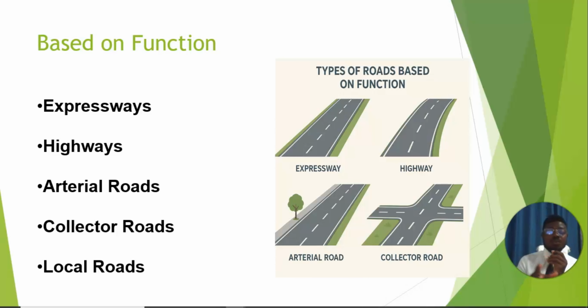That is one of the differences between an expressway and a highway, because the expressway is where we have high speed roads with controlled access, and we don't have any at-grade intersections. So the movement on the expressway is usually at higher speed compared to the highway, because the highway is just a major road for long distance travel.